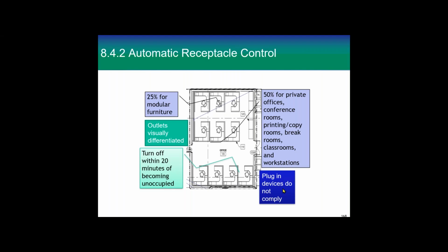All right. So the reason this is in here is we can get interval data from the meters of buildings. And we have requirements that when you go home at night, we go into a night setback on the air conditioning, the lights are off, just about everything you can think of, we try to control off. And then we look at it and the building's still using 50, 60, 70, 80% of the electricity it uses when it's occupied. And we can't figure out why, if it's complying with the code. So we think it's got to be plug load.